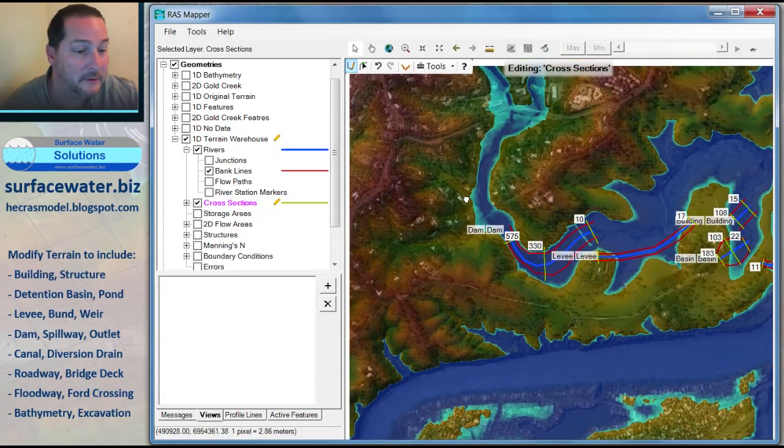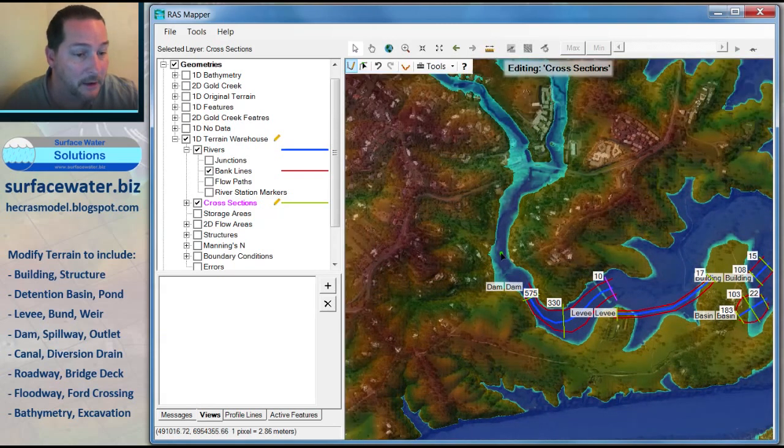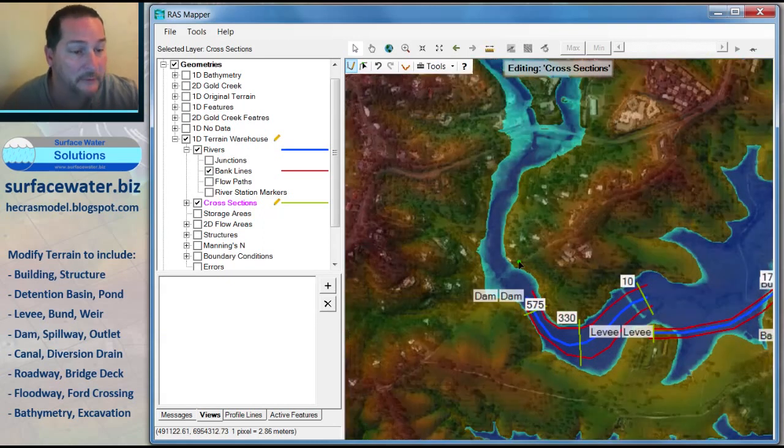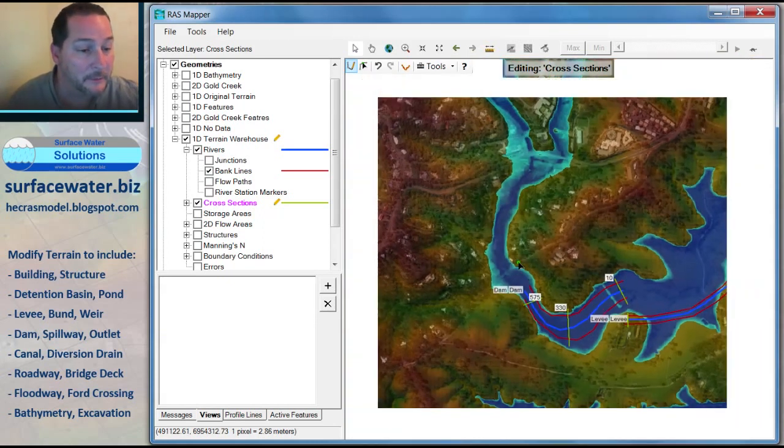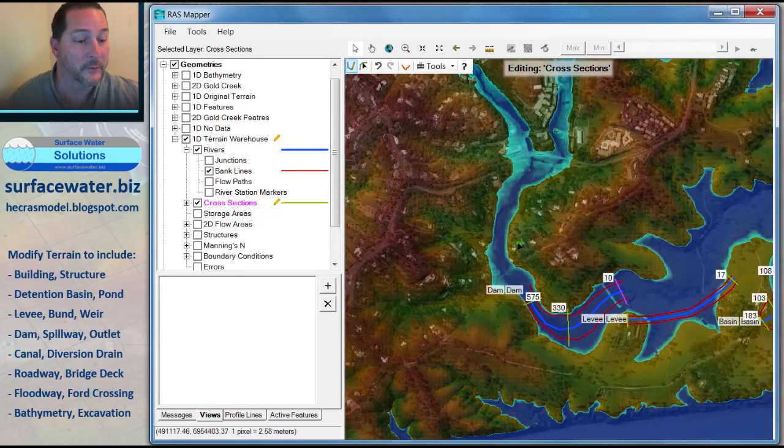Once I put the dam in up here, I might try and block up some water, prevent it from getting downstream, and I'll put a diversion up in this area as well. So if you were a dam designer, not many dams going in these days, but if you were going to choose where to put a dam, you might want to look for some narrow abutments that would store a lot of water behind them. In this case, we would be flooding out a whole lot of people, but this is just for fun.